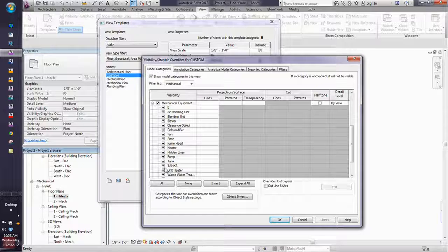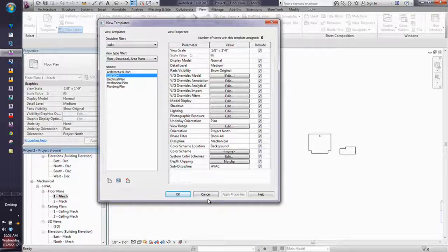No, actually what we wound up doing, how many of you guys are incorporating omni-class numbers into your parts? All right, let me give you a real big piece of advice. If you haven't been doing omni-class numbers, you need to do that now. Because a lot of the databases that the programs are going to be getting linked to, omni-class is one of the things that actually tells an item what it is.